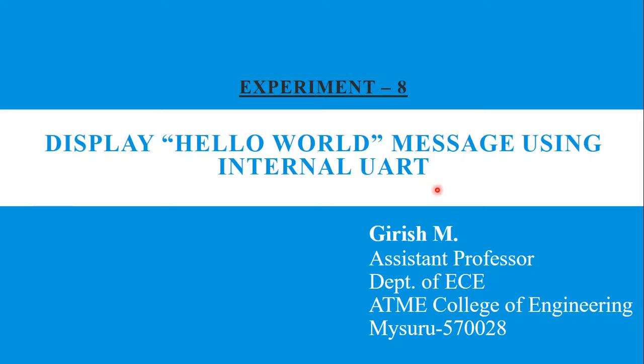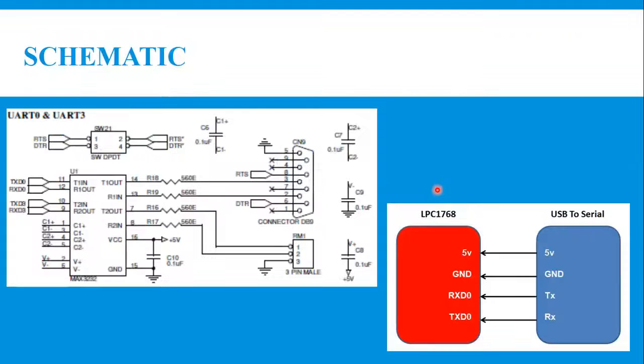The LPC 1768 has 4 inbuilt UARTs, namely UART0 to UART3. Here we'll restrict our explanation to UART0, and similarly you can extend it to the other UARTs. The only thing that varies is the pin numbers you are going to configure.